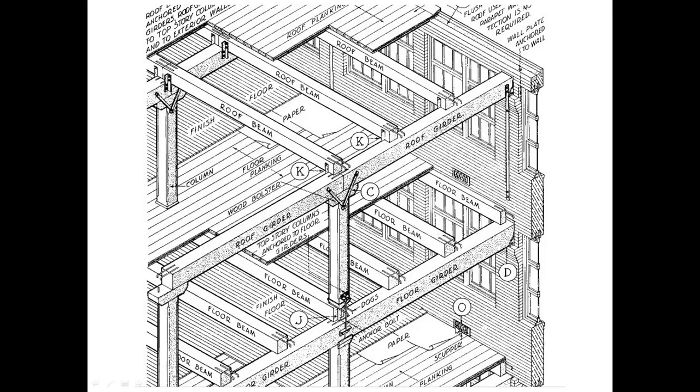You'll see these holes out through the brick. If you look through some of these old factories, you'll see these holes. If there was water, flooding of any type that would come in, rather than having it sink the floor, we have these scuppers. Scuppers allow water to escape out through the wall and prevent it from building up on the inside. So even in the old days, there were certain safety devices built into these types of structures.